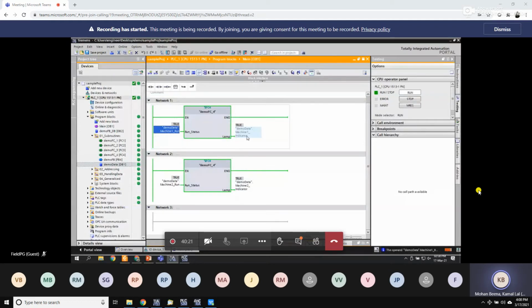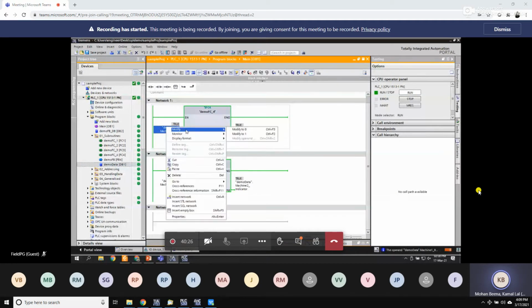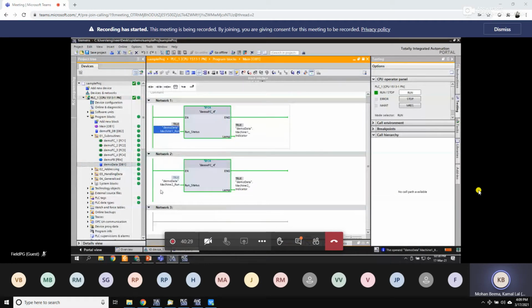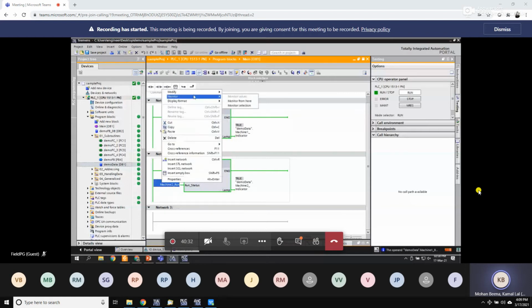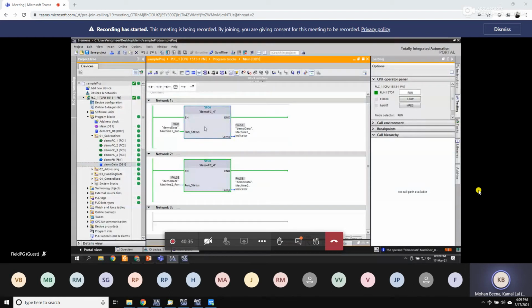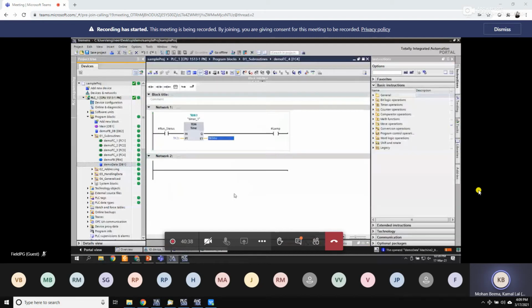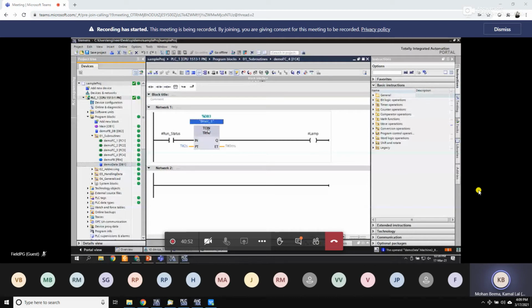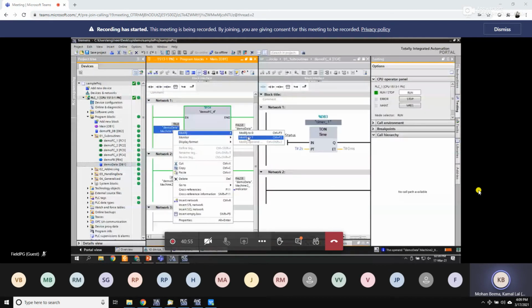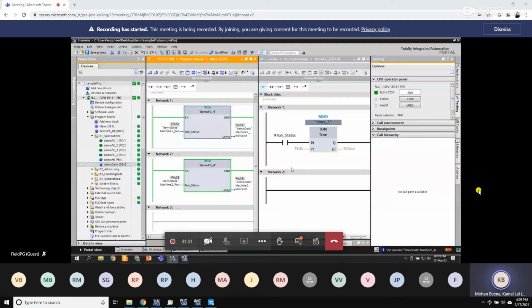So what is happening here? The only explanation for that is, in this particular case, internally, the timer that we are using is actually common, which you already saw, right? So if I open up this guy, for both the block calls, a single timer is actually working there with a static reference to this particular DB, DB3. So eventually in the main block, when the first network tries to turn it on, the second network tries to turn it off, and the same timer is pretty much confused until both the inputs are on. That's what was causing the behavior we saw.